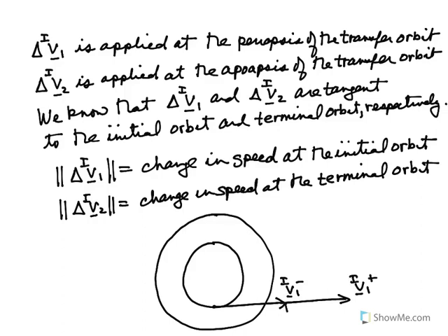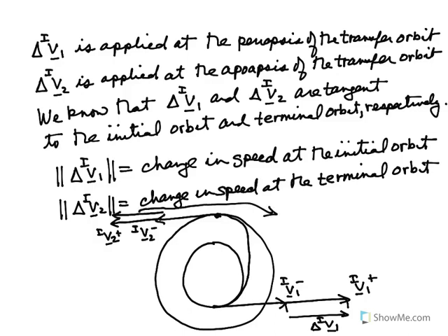So that amount right there is delta V1I. Similarly, now we get up to the final orbit. So we draw this transfer ellipse, we get up here. This direction is V2 minus I. And then when we're all done, we wind up with V2 plus I. So that vector right there is equal to delta V2I.